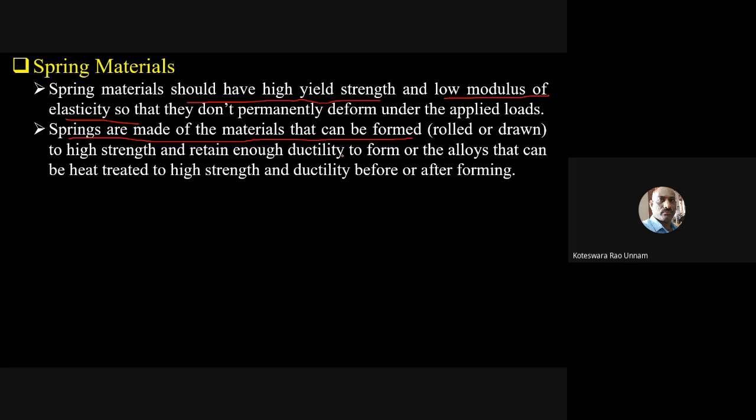So this is what I already told. The spring material should have enough ductility. If it doesn't have the ductility, then it is going to break. Suppose the spring material has brittle characteristics; since it is subjected to a fluctuating load, it is going to fail very easily, or with less life. The spring will have very little life if it doesn't possess the required ductility.